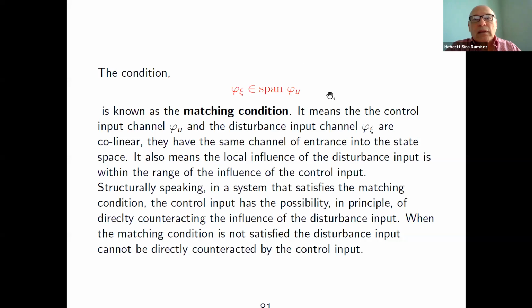So in the examples that you're mentioning, surely the voltage source can come from a number of different devices, like rectifiers that have some disturbances because there are periodic things that you cannot rectify. The rectification is not exact, and therefore you have some fluctuation around the mean value.